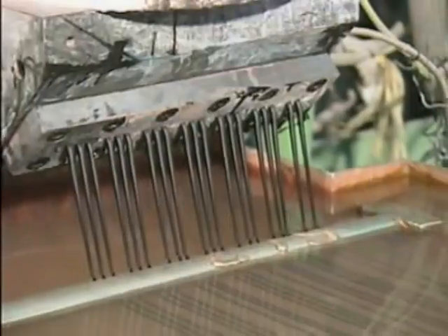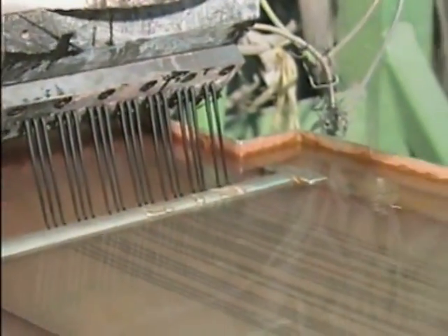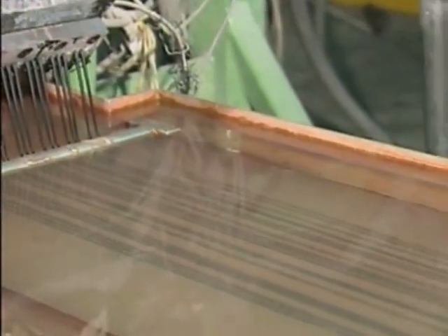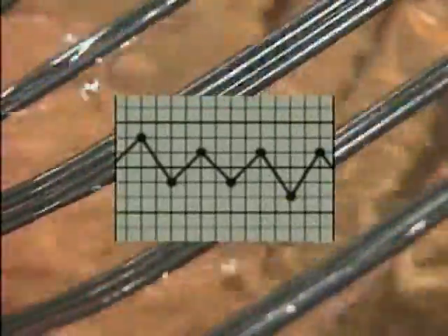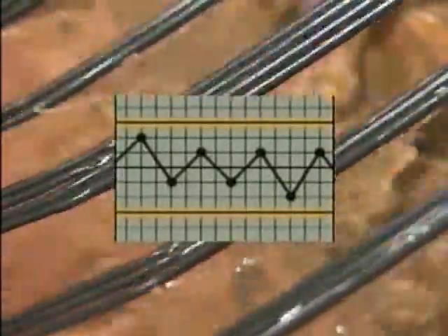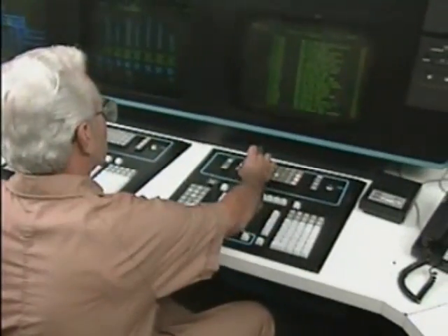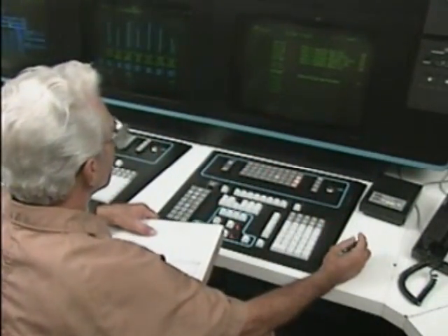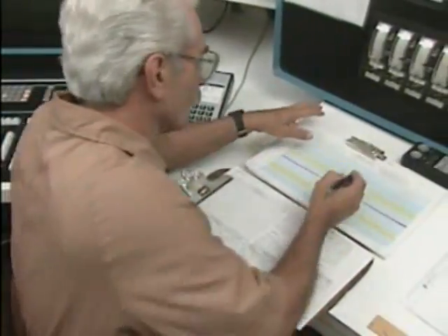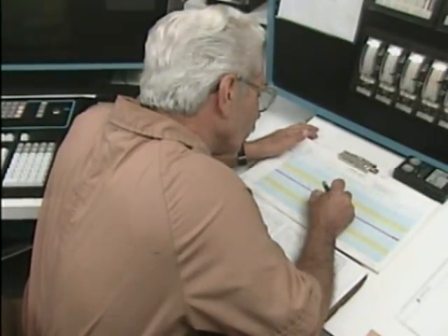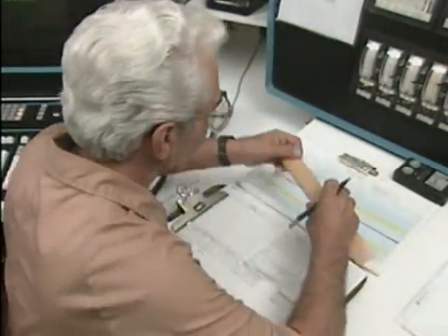Another step involves calculating the proper control limits for the process being monitored. Control limits are boundaries within which the process is controlled. While operators typically do not calculate control limits, it's important to understand that the data that's collected from a process should fall within these limits. If it doesn't, there's a problem somewhere in the process.